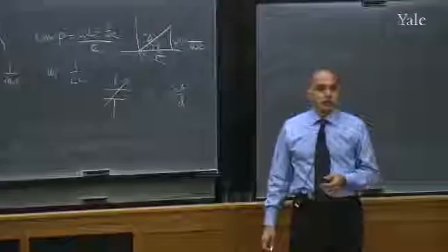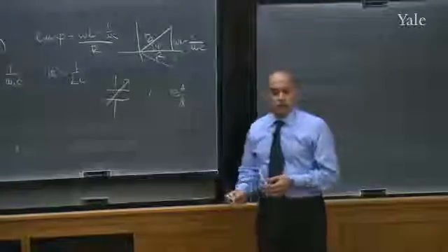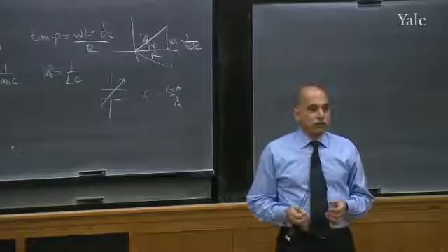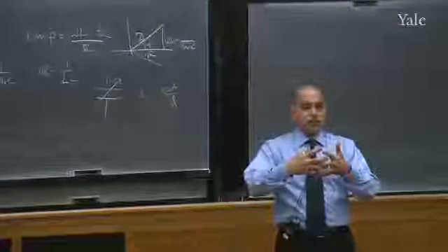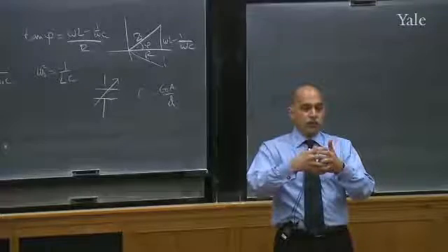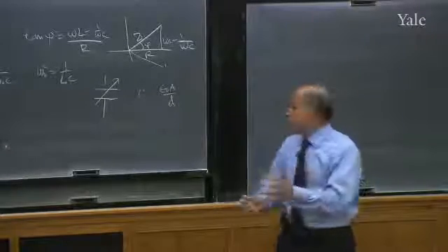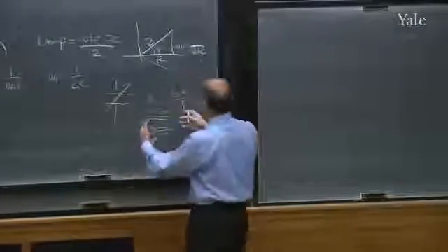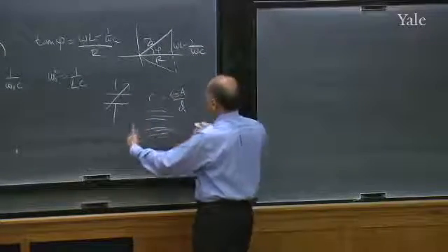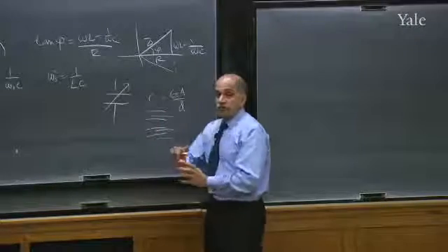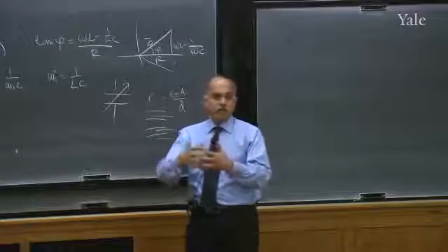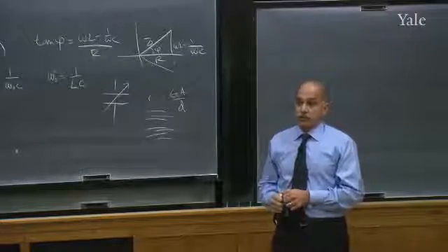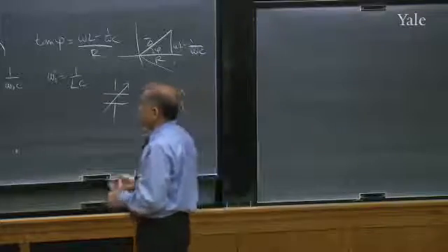Yep. You can change the surface area, but how do you think you can go change the surface area? Half circles, and then when it rotates around. That's right. You got these interlocking plates, and you can have them fully overlapped or not overlapped. You know, if you draw the plates like this, it's got many things, and these plates can be either really overlapping with the other plates or pulled out. When you turn the dial, the two things move in and out, and that varies the capacitance. That'll give you a range of frequencies, and that's the range you can hear. Okay, so that's one thing.